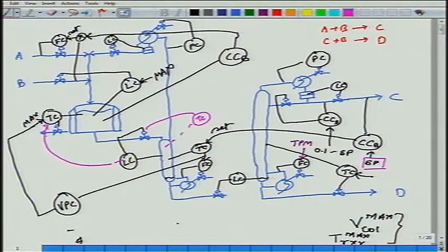This is what I had, right? Now I have level control this way, temperature control this way, and to keep boil up at max, I am indirectly controlling the temperature by adjusting what is happening in the reactor, but it is an indirect way of doing it.